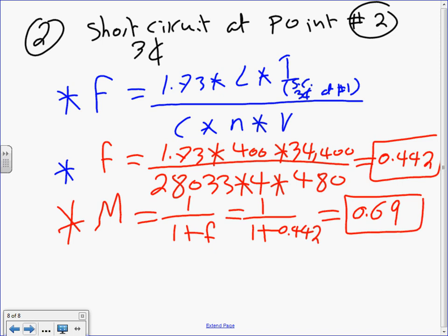Here's your percentage for cutting that short circuit. The short circuit has been cut down to 69% because of the impedance of the cable. A 400 feet run is a long run. Can you guys see how it's cut sharply? A deep cut because of the length. The impedance will act like a fuse, guys. Choke the current. Choke it. Cool?